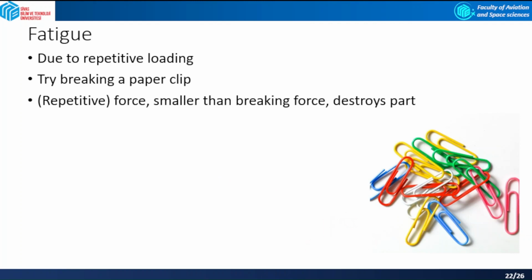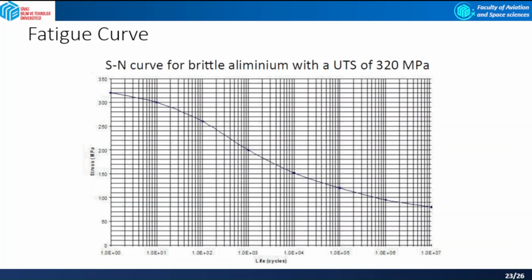in the metal structure. So this graph displays what's known as an S-N curve for an aluminum alloy. The horizontal axis represents the number of cycles logarithmically, while you have this vertical axis showing the failure stress. At the onset, during a static test, the material fails at a stress of 320 megapascals, this point.